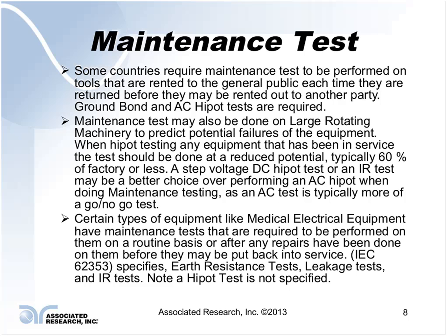In some countries, we've seen some European requirements where a maintenance test may be required on tools that are rented to the general public, where before the product can be rented back out to somebody else, they've got to perform a routine Hipot test on it as a standard test to make sure that it will pass both maybe a ground bond test and an AC Hipot test, to verify the ground conductor is in fact intact and good, and to also verify that the insulation within the product has not been damaged before it can be rented out to somebody else.